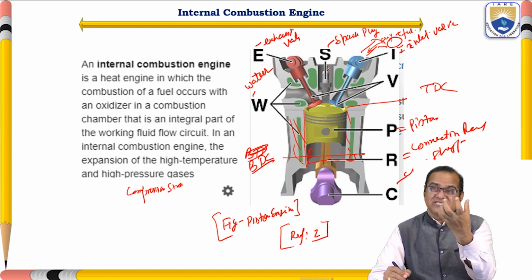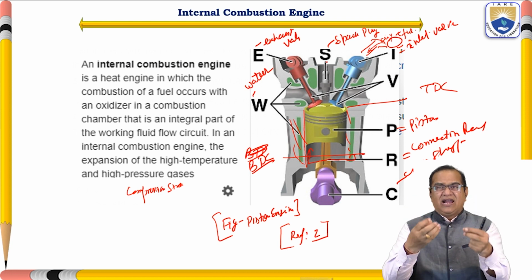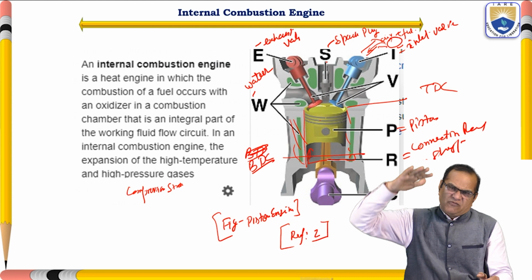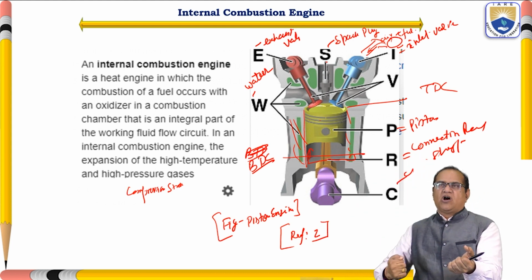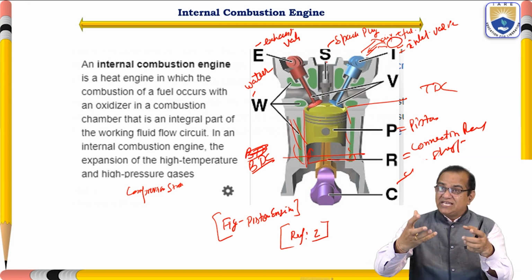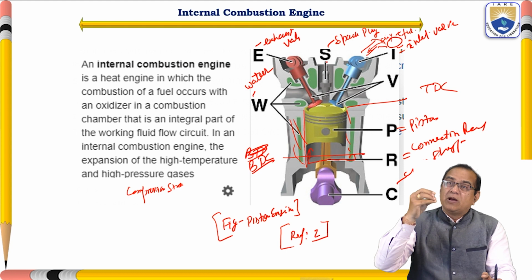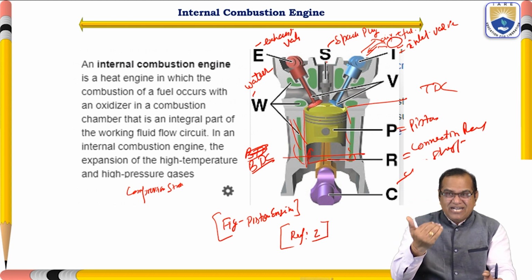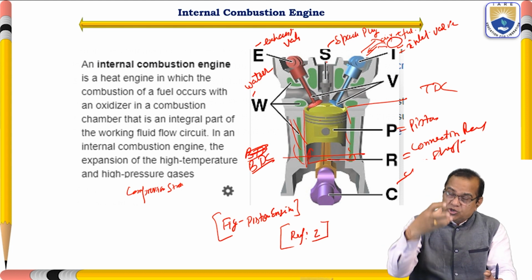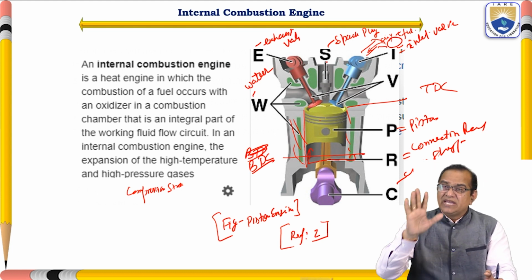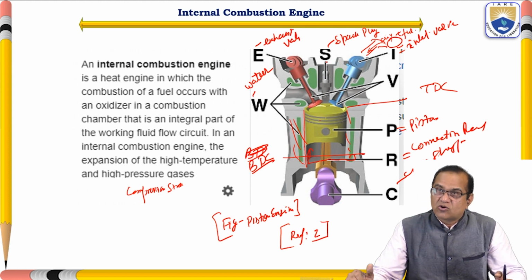So the petrol mixed inside this chamber burns like a blast, and a very high pressure is produced. So your piston will go down like this. When it is falling down with the help of the burning gases, that stroke is called the expansion stroke. In the expansion stroke, work is produced by the engine. In this case also, your inlet valve and exhaust valve both remain closed.